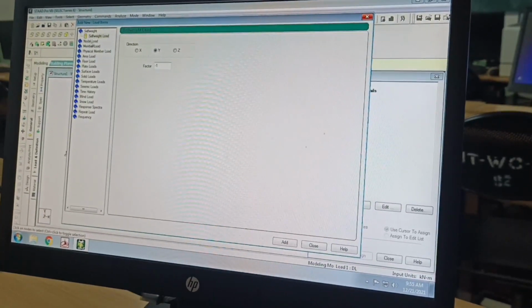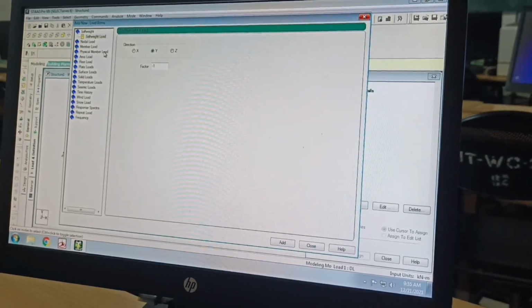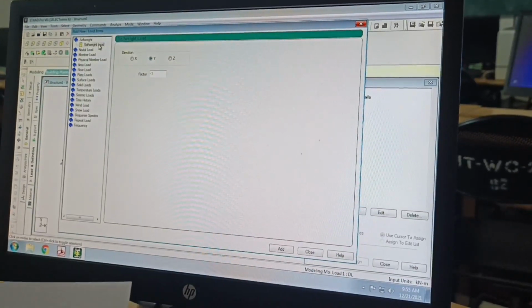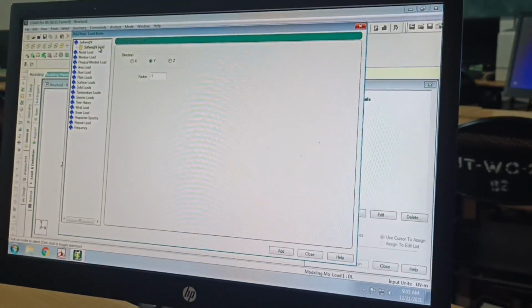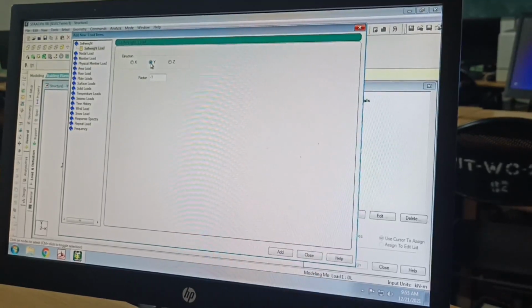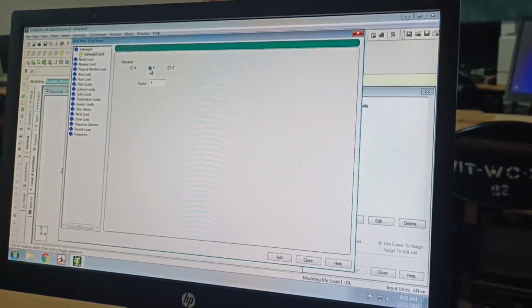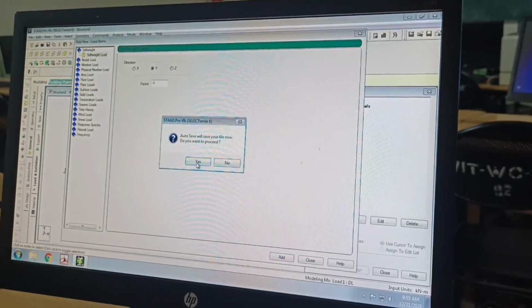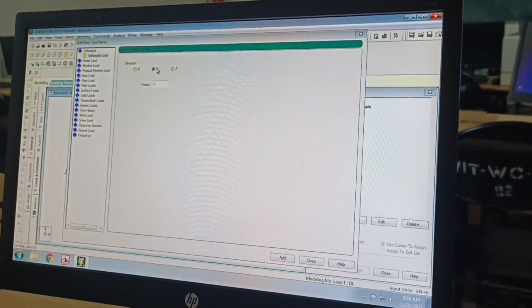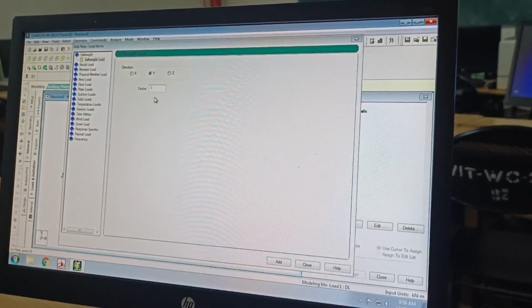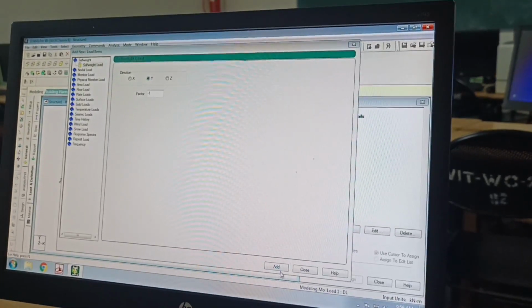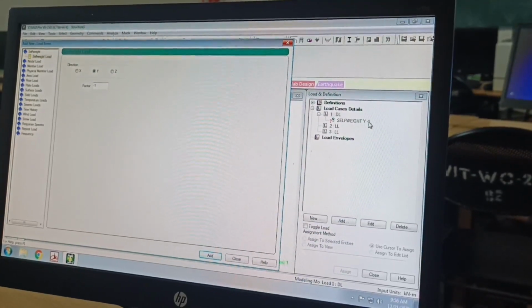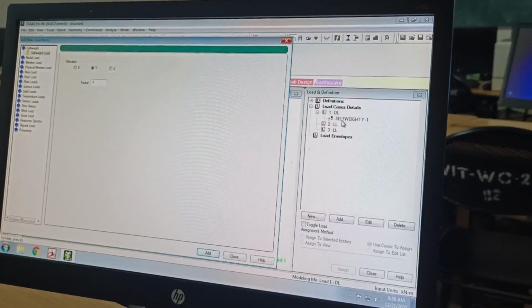This is the self weight of the load. Then there are nodal load, member load, and physical member loads. First we are only defining the self weight of the member. That load acts in the y direction, vertically in the negative manner, so we select the factor as -1. There are x, y, z directions, and we select only the y direction because the load acts downward in the negative manner. That's why y -1. Then click on add. Here on the right hand side you see the self weight in y -1, y direction. So that is the dead load condition.